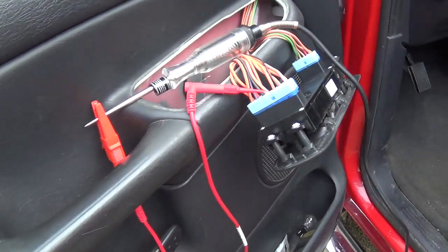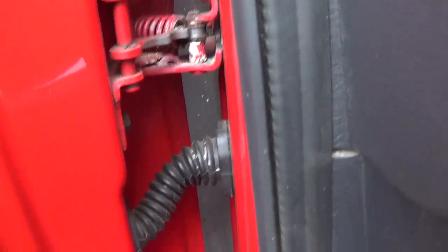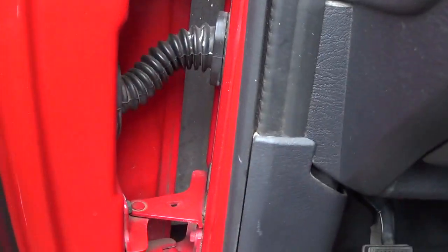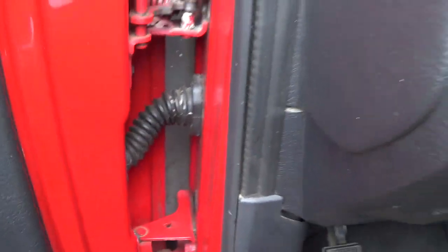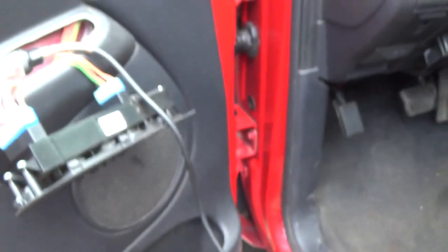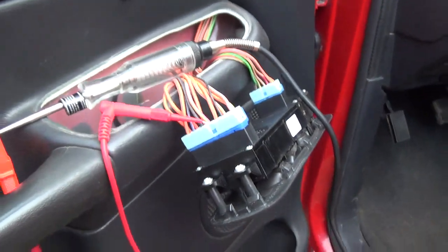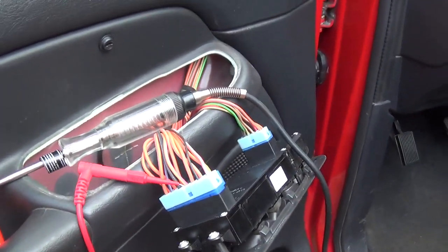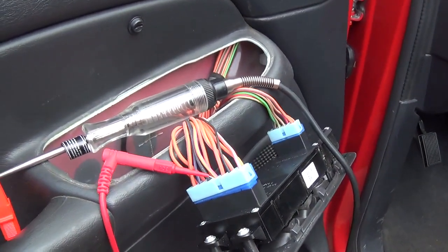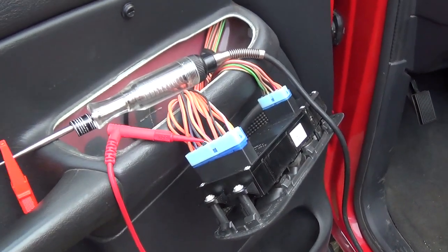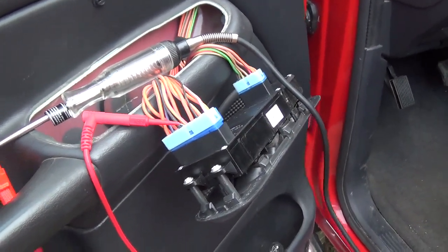Now, tracing that wire, obviously it's probably in here. All the Chryslers do it. They're probably broken wires right in this door hinge area because they didn't leave any room for them to bend. But to trace that wire and to fix it, obviously that's a separate charge. Now from here, can we 100% say, like, is the motor good? And is that rear switch also good? We know we have a broken wire.